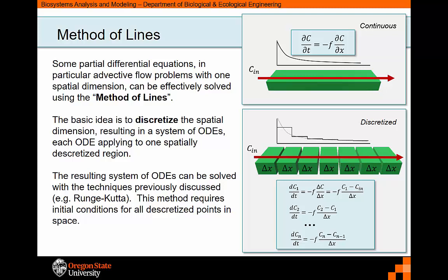As we see in the equations presented here, the concentration of C is related to the concentration in the upstream flow coming into a cell, as well as the loss from C to the flow out of the cell. Note that for the first cell, the inflow term is based on the concentration of the influent coming into the first cell. This would be considered a boundary condition.